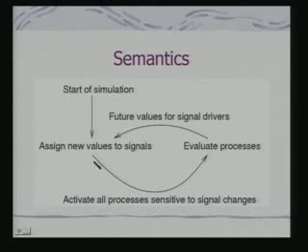So this is the basic semantics. You start a simulation, assign new values to the signals, and evaluate the processes, which will now provide the future values for the signals because they will be connected. That value comes to the signals, and that way you simulate and activate all processes sensitive to signal changes.